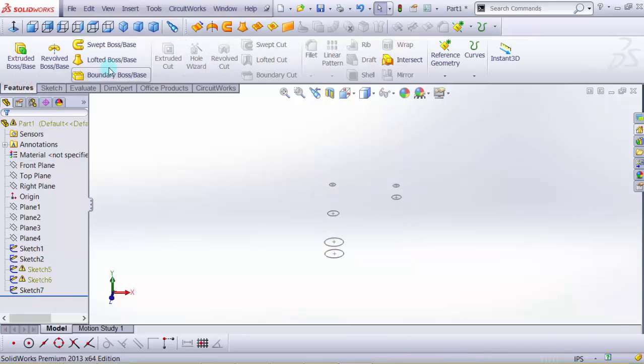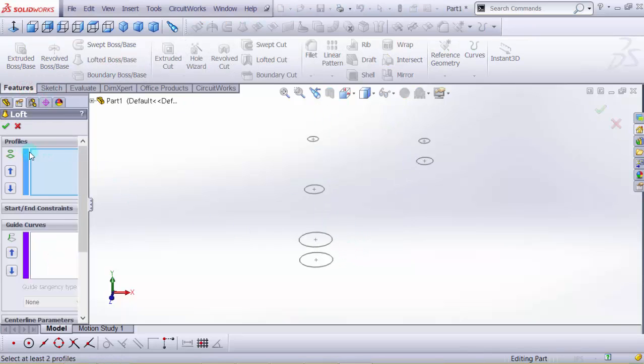Okay, loft. And now let's learn a couple of things here, because this is gonna help you later when I make references. If I say path, you need to know exactly what a path is. If I say profile, you need to know exactly what a profile is. So let's teach you guys now, so that later on I'm not gonna explain myself. You just have to know it. So profile is a closed loop, and path is an open loop.